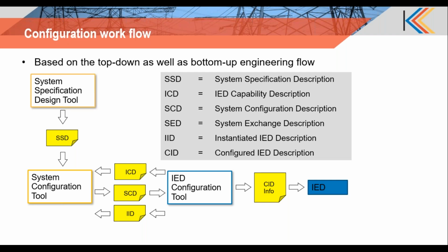So for that, we have the concept of this SED file, which is extracted information from your SCD file, which contains only those information that are required by the other project in order to do the configuration. So that is the SED file. So that is a subset of your SCD file, the master configuration file. So the SED, or the system exchange description file, is a subset of your substation configuration description file.